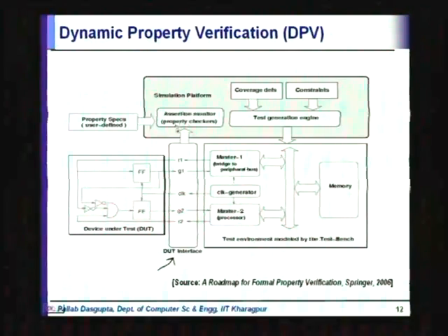Right. So, this complete simulation runs like this, that the test environment drives the inputs into the device under test and samples the outputs of the device under test, but this whole interaction takes place through the interface, and the monitor actually reads the samples the signals on the interface and checks whether there is any violation of the properties. Right. So, as the simulation progresses, it keeps tracking all these properties, and whenever there is a violation of any property, it flags an error.